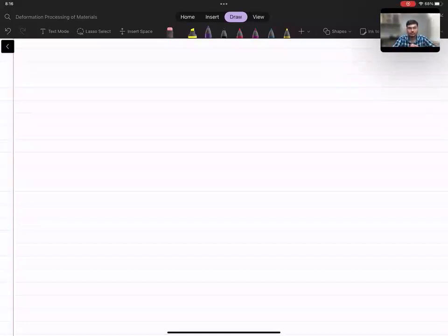That happens in the case of bending also. Suppose we have bent a blank like this, and after the removal of load, it would regain some of the strain or deformation, moving towards its initial shape to some extent. So we need to consider that elastic recovery also, and for that we provide the bend allowances in case of bending operation. So let us see bend allowances.